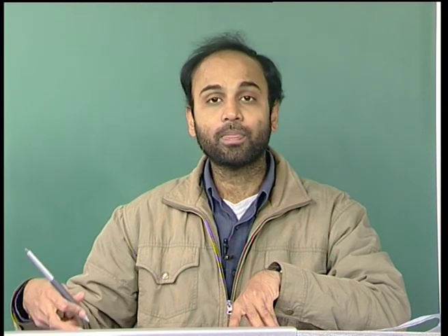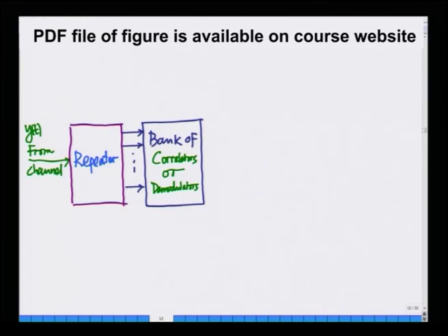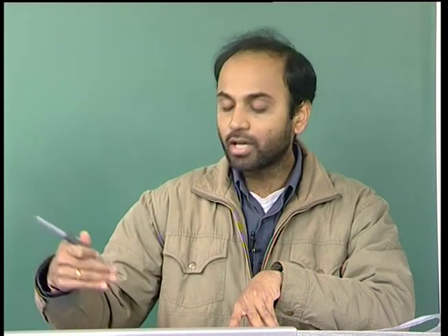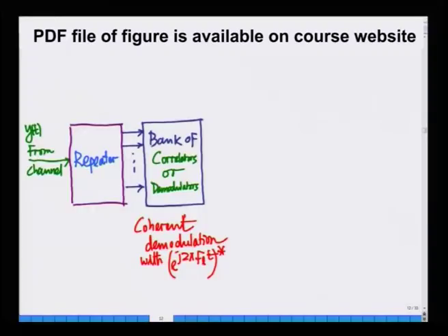This is essentially doing coherent demodulation with the appropriate subcarrier. So, what this carries out is coherent demodulation with e power j 2 pi f_l t conjugate. Remember, for the lth demodulator, I am coherently demodulating the lth stream, which is e power j 2 pi f_l t conjugate, multiply and integrate. That is the same thing, that is a correlator, essentially the structure we went over. Now, at this output we have the n symbols corresponding to the n streams. In fact, these are the n information symbols.